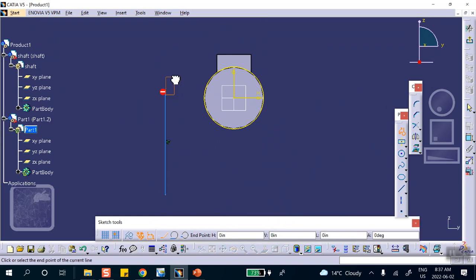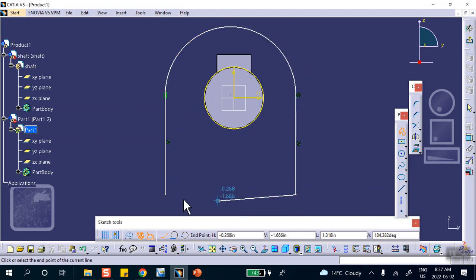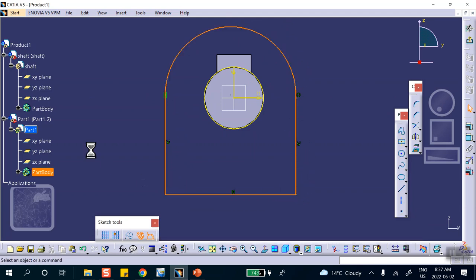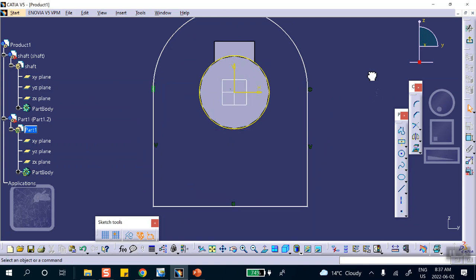Something like this, and like that, and this, and that. I want to make sure it's symmetric, concentric here. So this circle controls that circle, because I know that the centers are probably not in the same place. You can see that it's a little bit shifted. I want to make it concentric.